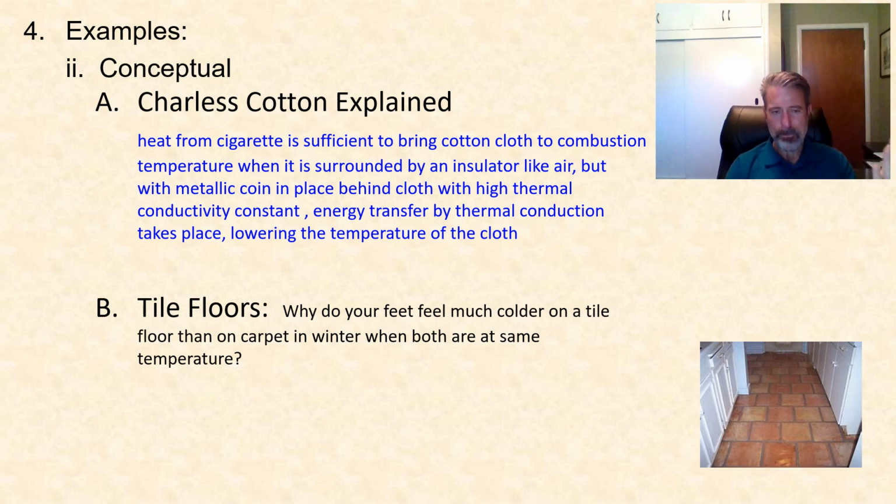Well, just so you realize, it's not that the tile is at a lower temperature. Think about thermal conductivity. The tile is a much better thermal conductor than the carpet, which means that it allows heat transfer from your feet to the environment to take place at a much higher rate than when you're standing on carpet.